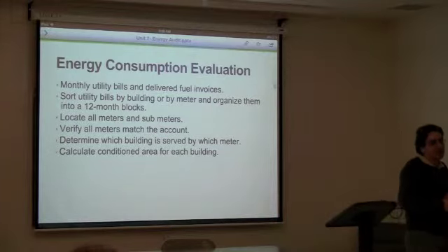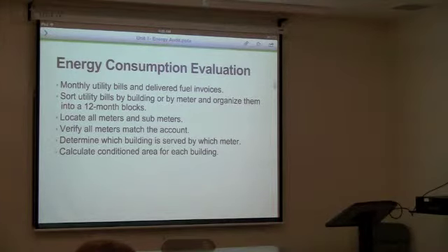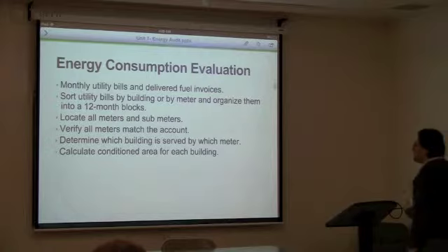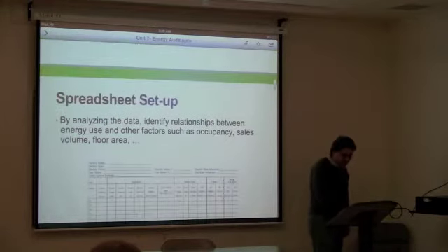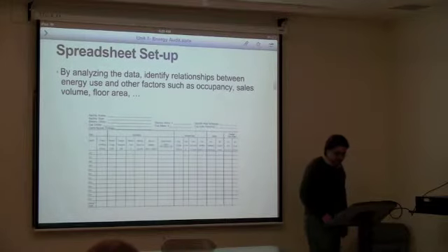Most likely you might end up doing some measurements. The best scenario is if there is a possibility to add a meter, but it costs money, several $100, and shutting down the operation for a while, but add a meter for a major energy consumption unit. If you can do that, it's beneficial forever.